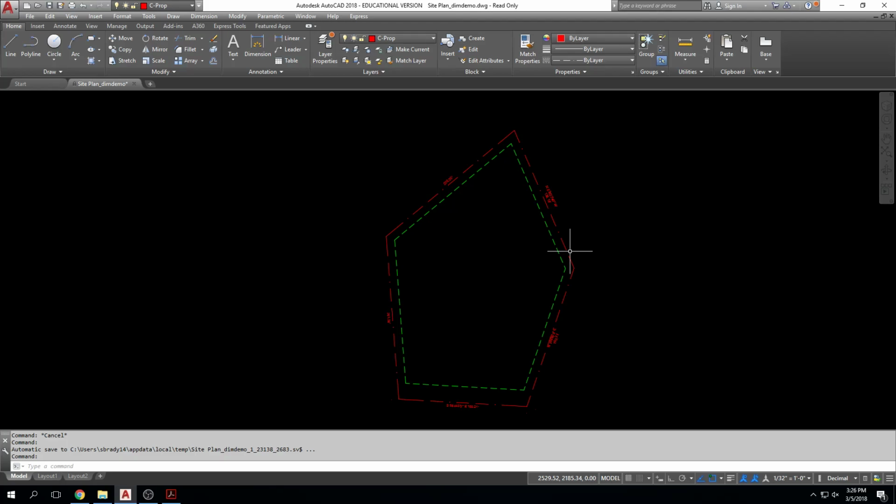It seems to be architectural. I think so. Nope. Something is wrong with your dimension style. It has to be because everything else looks good. You may just need to create a new dimension style from scratch and see.